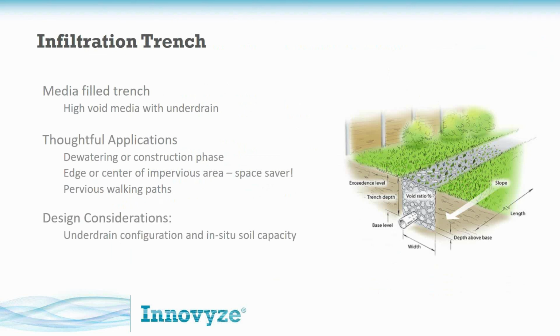Considerations: you've got to really assess the hydraulics of this system. The underdrains, the material, and likely there's a filter fabric involved, right? We need to be able to assess those, again, above and below the facility. Maybe there's soil underneath, which has some infiltration capacity.